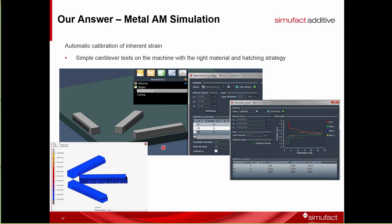Then you build one of these specimens, cut it off or cut it in between, and measure the deformation that occurs after you cut it off the base plate. We take that information and perform a little design of experiment simulation with finite elements, and we back calculate what the inherent strain is for your process, your machine, your powder, and your parameters. We can do that relatively quickly.